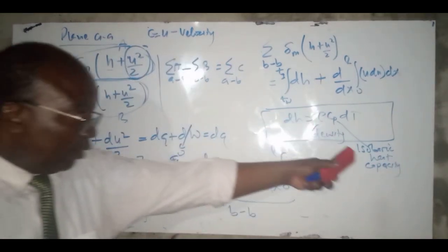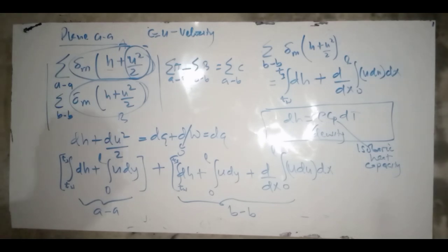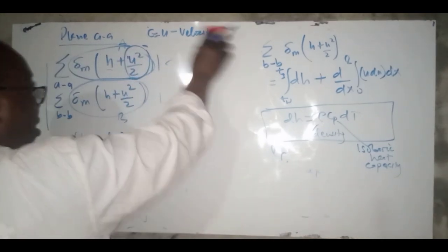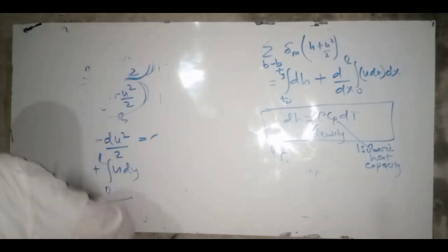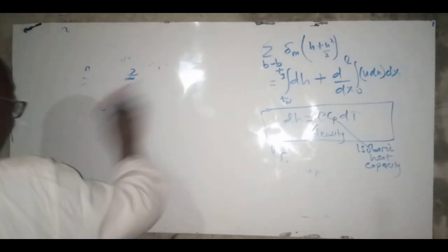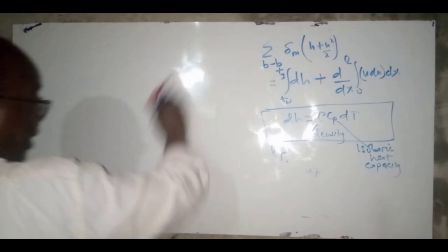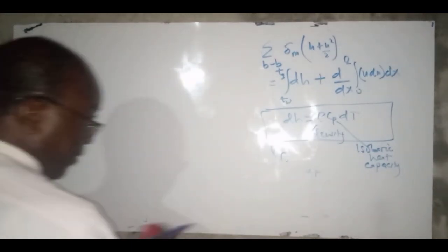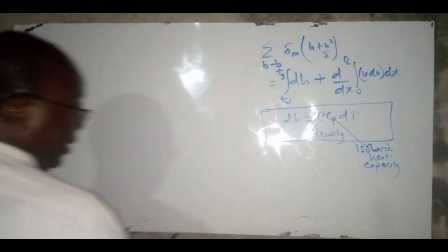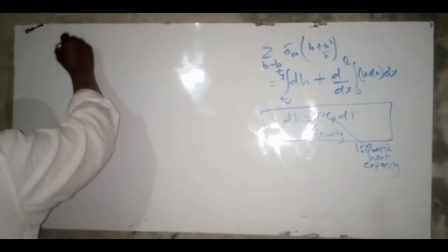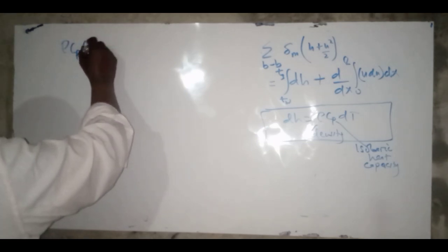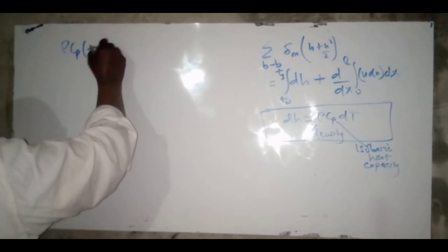That is density, that's isobaric heat capacity. So let us see how we now apply this. And remember, all this has to do with specific enthalpy and specific kinetic energy is all equal to the heat transferred. Now, say all that is equal to the heat transferred. That is rho Cp temperature, that is Ts minus Tw,